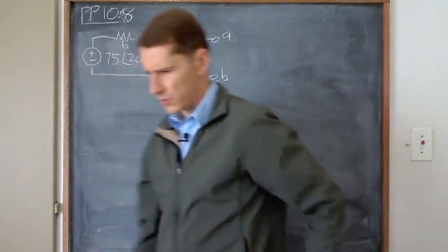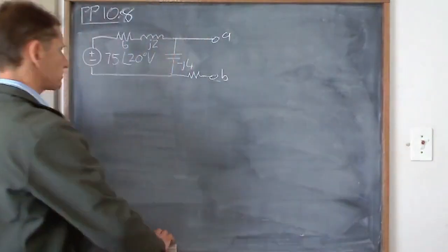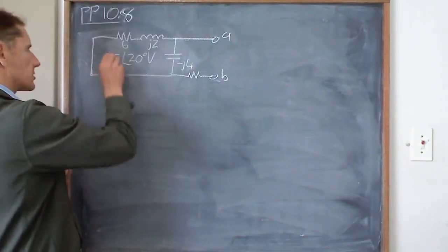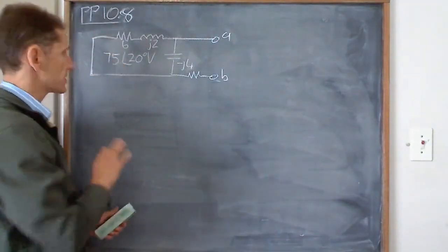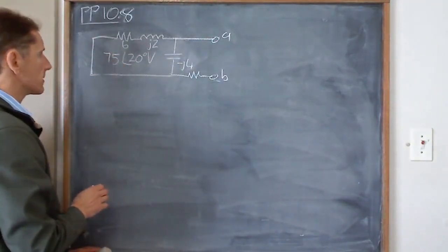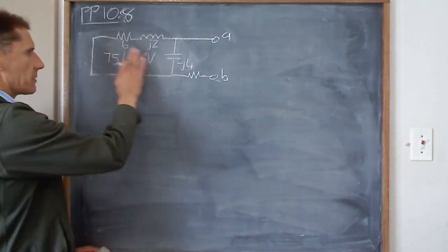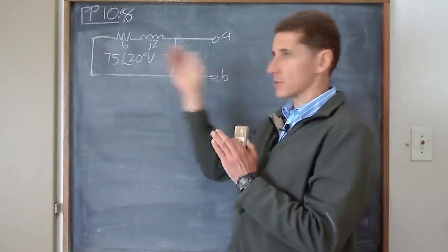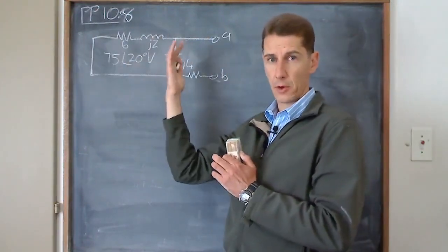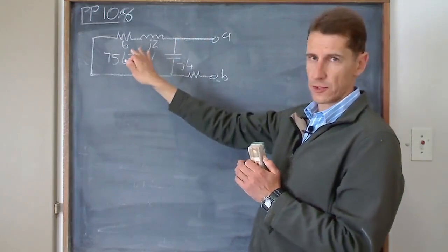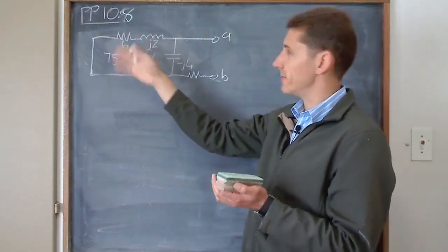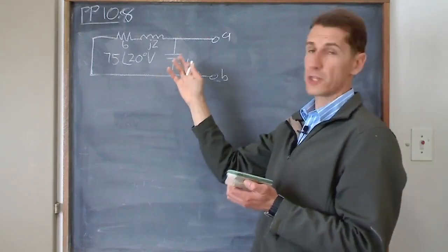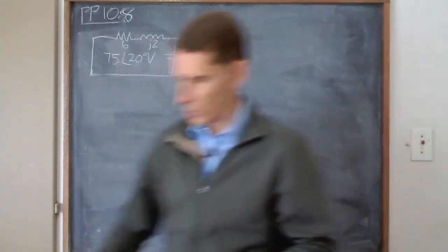Okay, so let's do the Thevenin impedance first. For that, you have to take your voltage source, and it becomes a short circuit. For the sake of space, I'm not going to redraw my circuit now. So that then becomes 0 volts. What do you see when you're looking in? Now I need to simplify from that direction. The 6 plus j2 are obviously in series. That combination is in parallel with a capacitor, which then will be in series with a resistor.